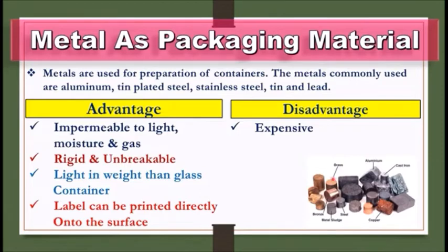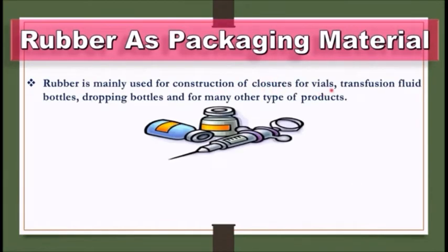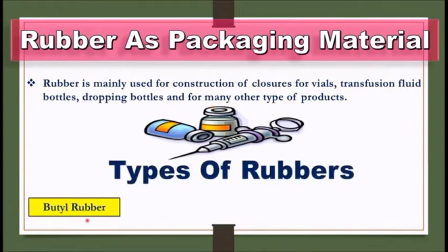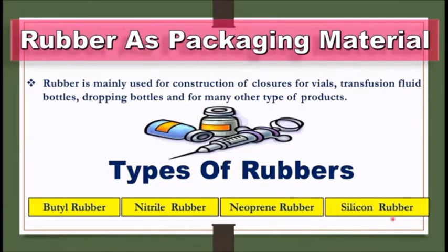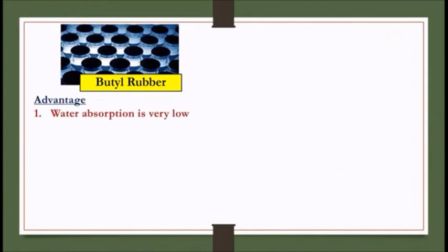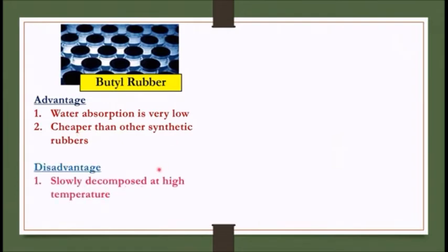Next we see that plastic containers are made up of polyethylene. The density of polyethylene ranges from 0.91 to 0.96, and it is susceptible to oxidative degradation during processing, so antioxidants are added like butylated hydroxytoluene, that means BHT, and dilauryl thiodipropionate.